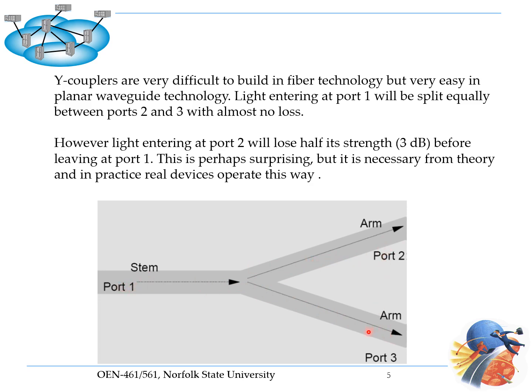What is interesting here is that in the direction when we start from the left and see how much light we will have in port 2, it will be 50%. So our losses will be 3 dB. But what if we couple light from port 2 to propagate to the left? How much light will enter port 1?